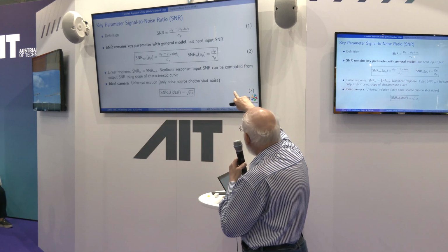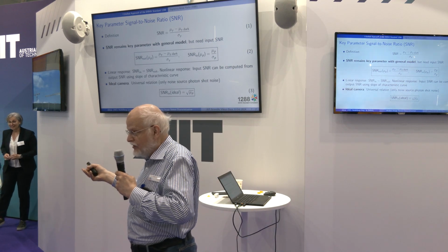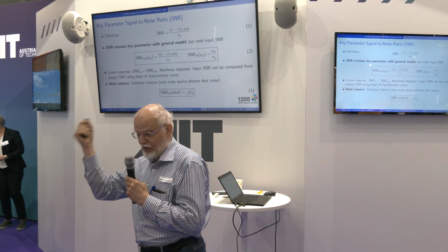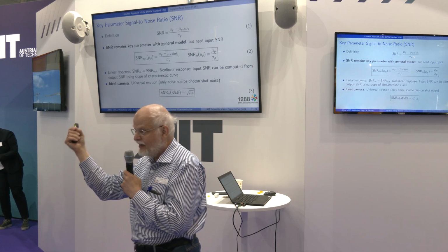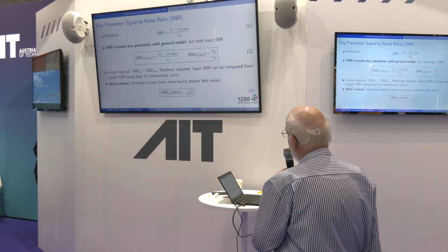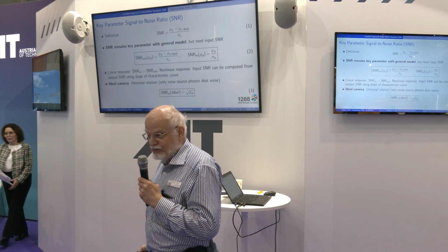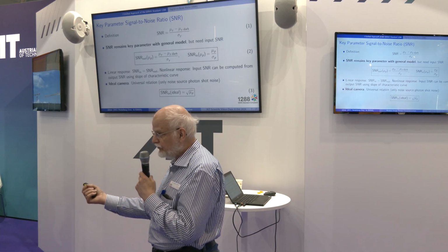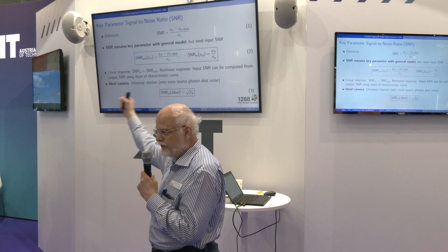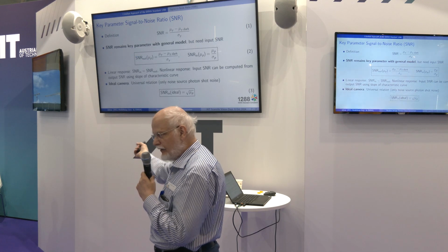That means the mean number of photons divided by the standard deviation, how good we can measure it. You are not interested really in DNs, you are interested in how bright is actually what I am measuring and how good can I measure this brightness. That is what you want to do. If you have of course a linear response, then things are easy. That is what we are used to. Then noise and signal is amplified by the same factor, and the input and the output signal are the same.